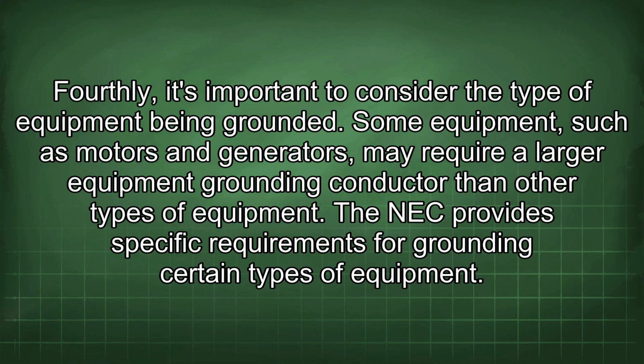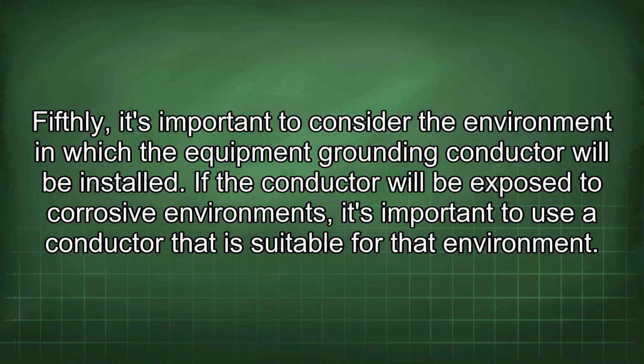Some equipment, such as motors and generators, may require a larger equipment grounding conductor than other types of equipment. The NEC provides specific requirements for grounding certain types of equipment. Fifthly, it's important to consider the environment in which the equipment grounding conductor will be installed. If the conductor will be exposed to corrosive environments, it's important to use a conductor that is suitable for that